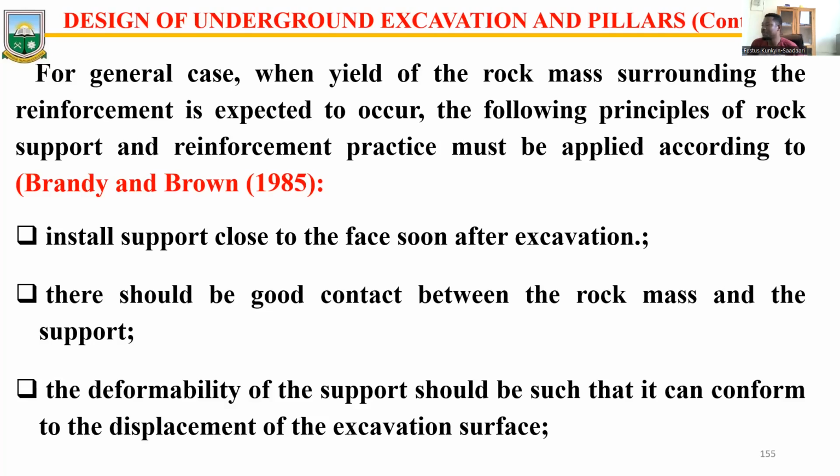For the general case, when yield of the rock mass surrounding the reinforcement is expected to occur, the following principles of rock support and reinforcement practice must be applied. So, one, install the support close to the surface soon after excavation.